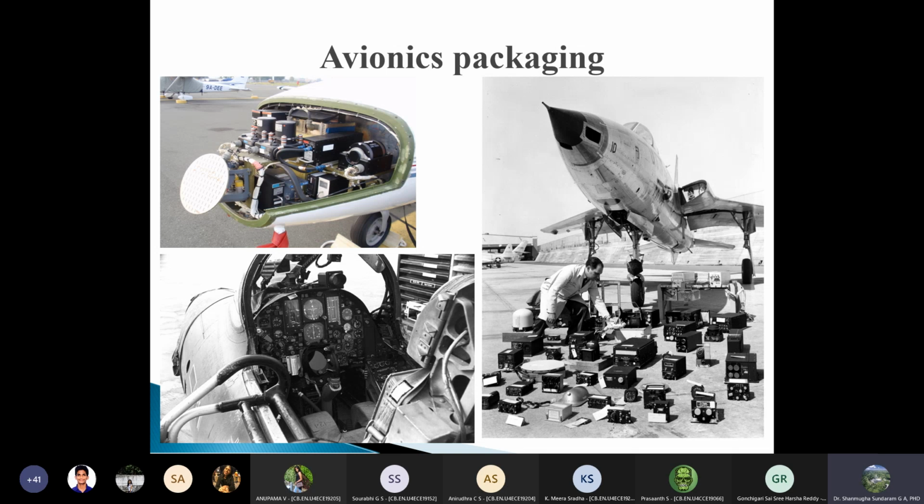So you will notice that packaging comes in various standards which are specified as ATR with an alphanumerical representation following that. And there is yet another scheme that is implemented, which is called the modular concept unit, MCU. So it is either as ATR or MCU that you will have the line replaceable unit configuration defined in aircraft systems.